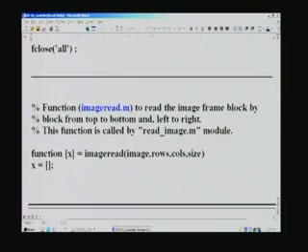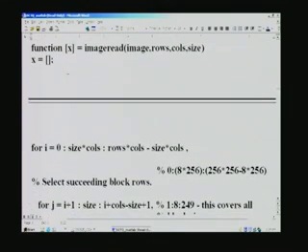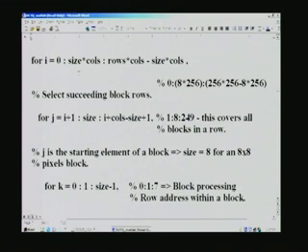The image read is the function we had called earlier, and that is what is declared here. Once again that is available as x here, and we initialize by converting all elements to 0. Once again we have for loops here. The first loop: we have already got one block of pixels, and there may be several blocks along the horizontal dimension of the image. We call that a row block. It is a row of blocks, which means there are 8 rows there. So 8 into 256 pixels will be covered in one row block, which you should understand.